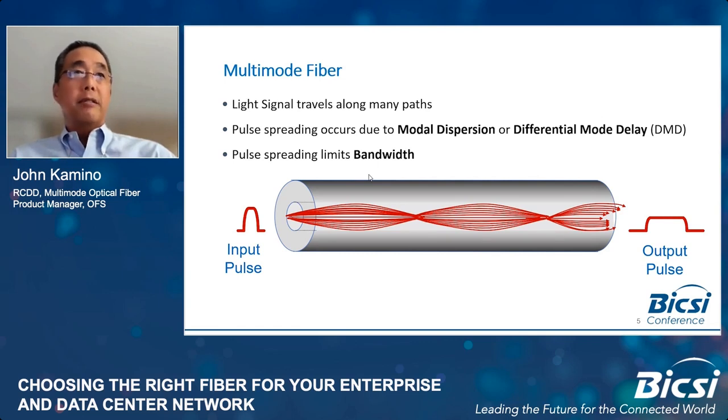You can see when looking at this fiber that light traveling directly down the center of the core has a shorter path than light that's traveling along the core clad interface and being reflected from side to side. If they all traveled at the same speed, then the light traveling down the center of the core would arrive far earlier than light taking the longer path.